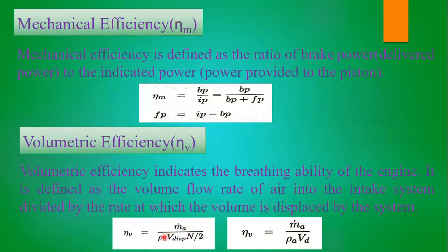Okay, so what is the volumetric efficiency? Nothing but mass flow rate of air by displacement. Here density also creates a major impact. I already said volumetric efficiency is going to depend upon density. If the density of air is high, the volumetric efficiency is going to reduce here. Why? Because the residual gases are there, which come into action. If the residual gases are less, there is more space available for the air to get into the combustion chamber, right? So density of air is also going to create some impact on volumetric efficiency here.